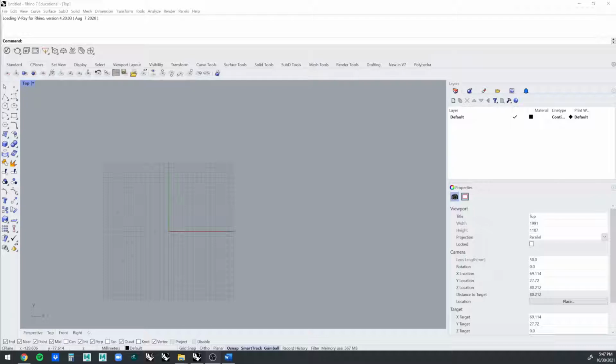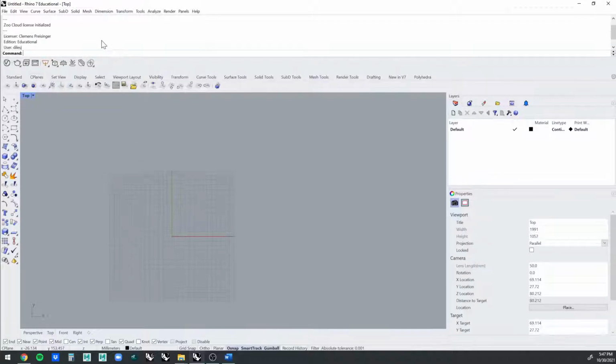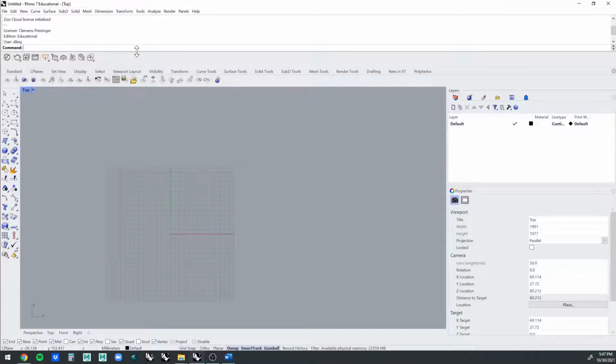The first thing you need to do is pull a license and open a blank Rhino document and type Karamba with a K, K-A-R-A-M-B-A, 3D get license. This will pop up. And if it is licensed successfully, you will see some text up here. It may take maybe 30 seconds. Rhino might freeze during that time while it pulls the license.